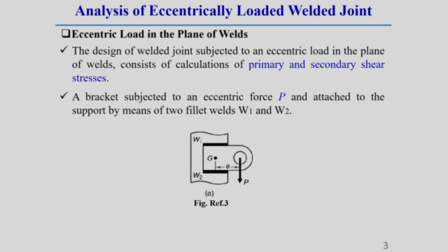Eccentric load in the plane of welds can be described in the following way. Let us consider a bracket, which I am interested to connect with another plate. This bracket I am representing as 1 and this is another supporting plate 2. Once I go for connecting these two components, what is required to do? You have to do some welding operation.